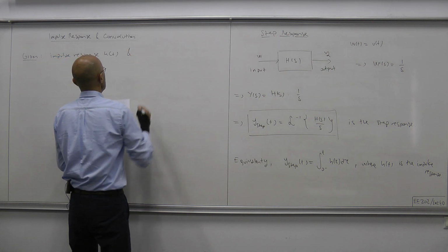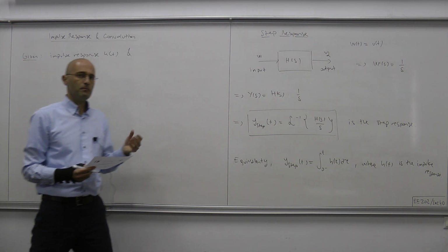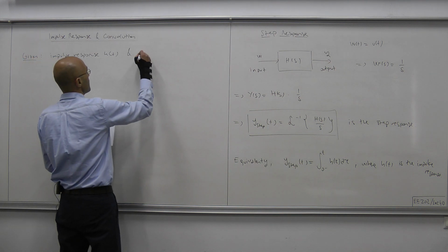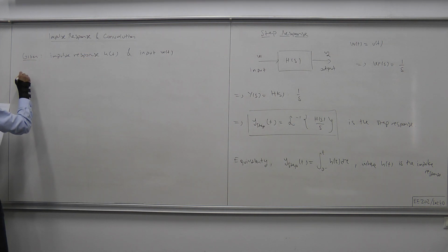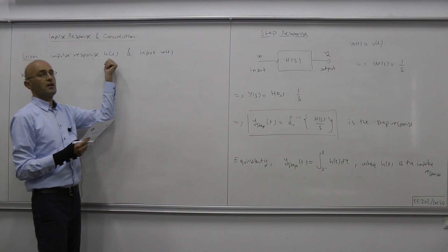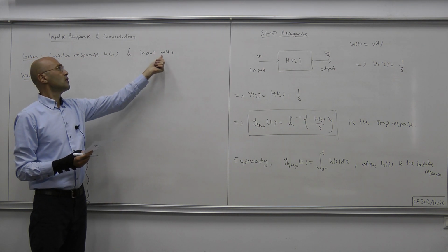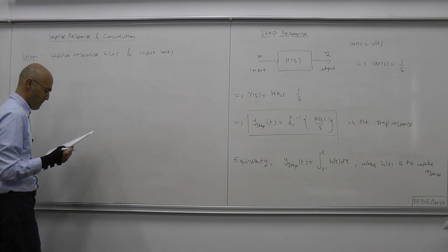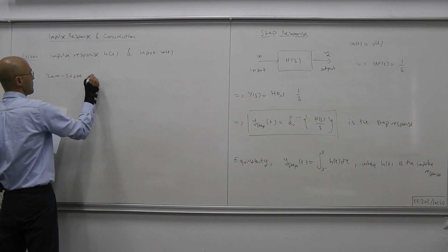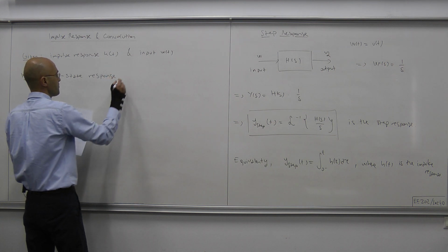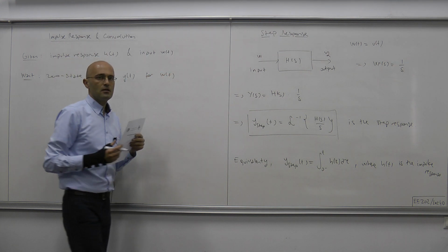And what we're interested in is the response of our system to some particular input w of t. So that means what we want is, given this information h of t, the response, or the zero state response, y of t of our circuit to this arbitrary input w of t, when the driving force is w of t.